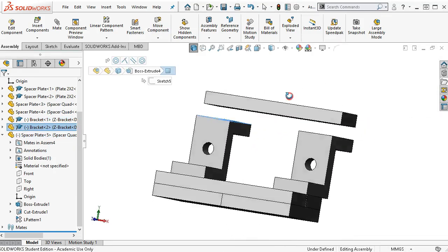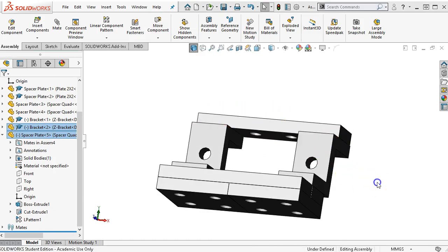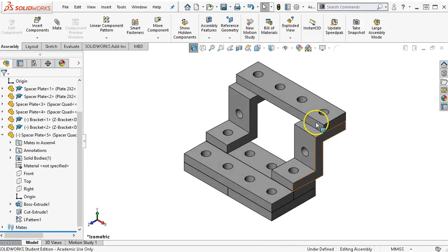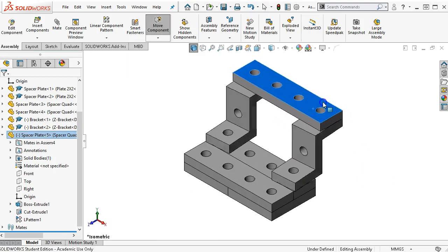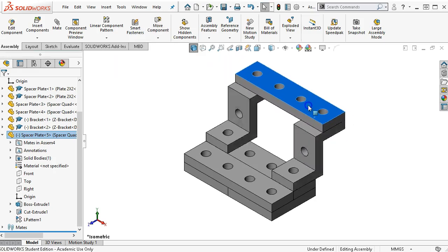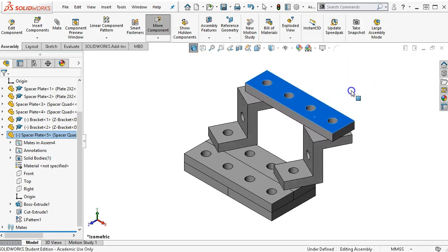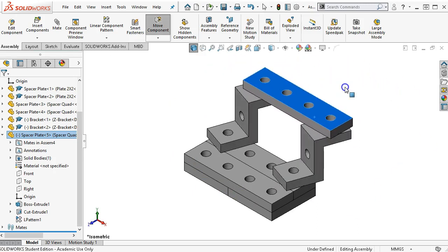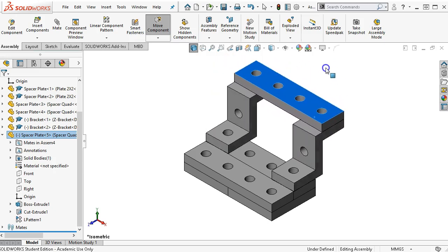And then because those are faces, we'll rotate over and go coincident. Alright, so the more natural movement is the same as with it being parallel. If I suppressed or deleted the parallel, this would still work. This would still have that rotation because it's relying on those pegs for its position, its orientation within the assembly.